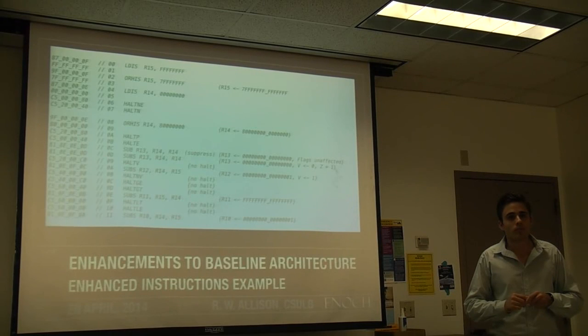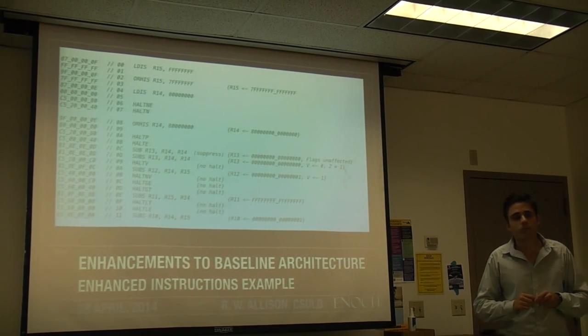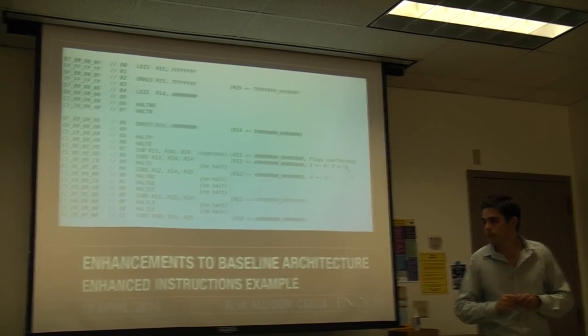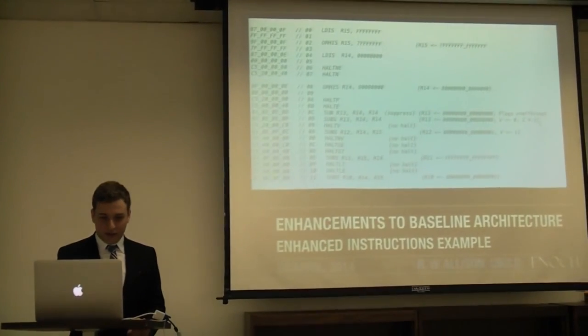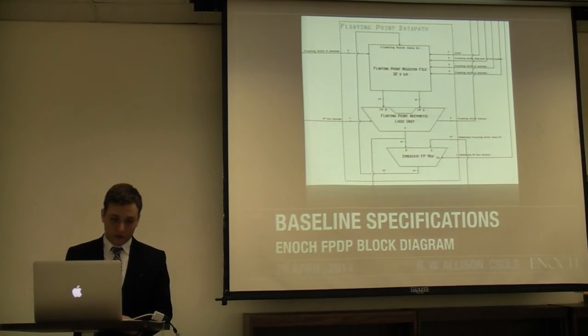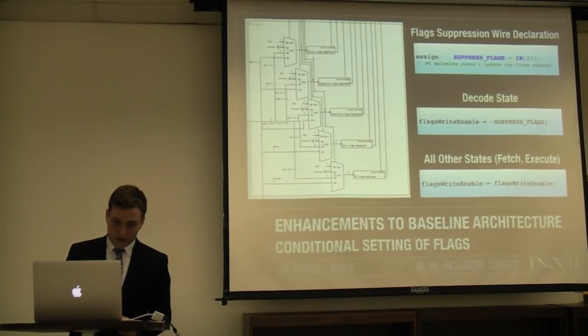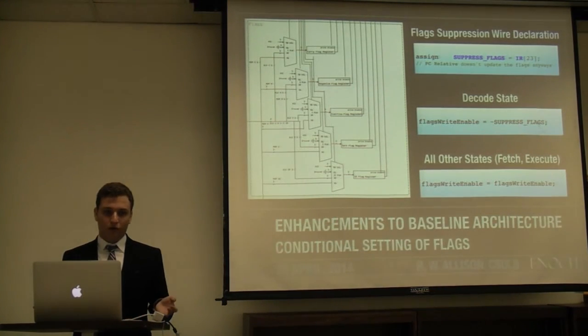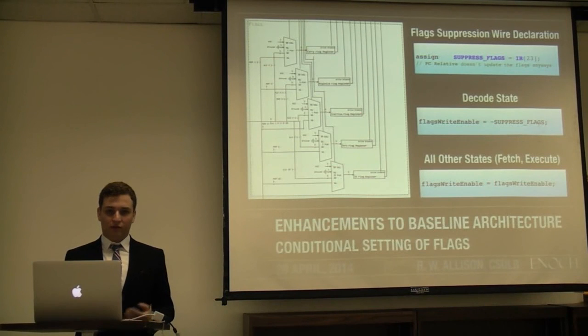Partially, yeah. But I was curious how exactly you are setting the flags on the loads, but I'm taking a second look at it now, and I think I understand your code more. On the loads, the flags aren't actually taken from the ALU, as Sam said. There are additional comparators so that we wouldn't have to go through the ALU and add additional muxes into the ALU, because we may want to use the ALU for something else while still loading something in.